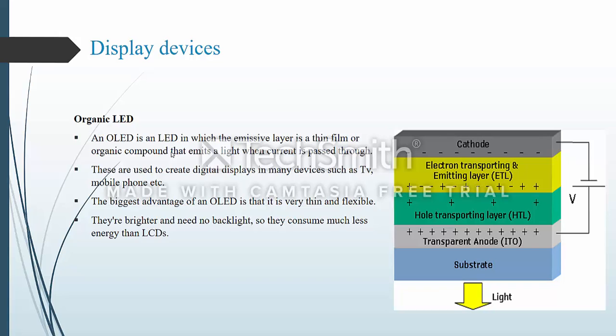Positive holes are much more mobile than negative electrons, so they jump across the boundary from the conductive layer to the emissive layer. When a hole, a lack of electron, meets an electron, the two cancel out and release a brief burst of energy in the form of a particle of light, a photon in other words. This process is called recombination, and because it's happening many times a second, the OLED produces continuous light for as long as the current keeps flowing.